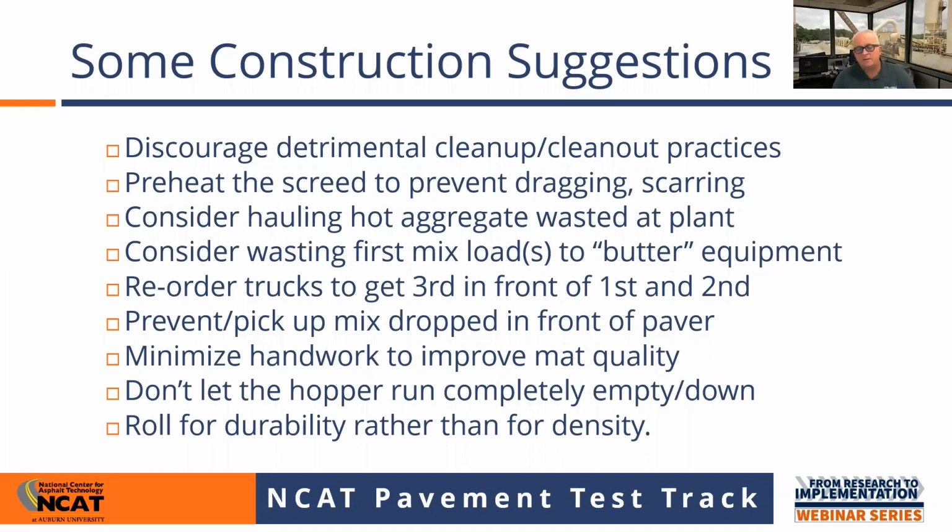And then finally, this is really important. It's a big deal because sometimes our field crews get a little carried away and they think, well, we're going to do our jobs well. We're really going to roll this surface and make sure that we've got it good and stable on the roadway. But you need to roll for durability and not for density. And that's something that on the material side, the engineering side, and the planning side, we know, but you've got to communicate that to the field crews.